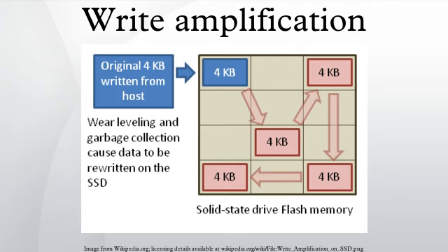Limitations and dependencies. The trim command also needs the support of the SSD. If the firmware in the SSD does not have support for the trim command, the LBAs received with the trim command will not be marked as invalid and the drive will continue to garbage collect the data assuming it is still valid. Only when the OS saves new data into those LBAs will the SSD know to mark the original LBA as invalid.